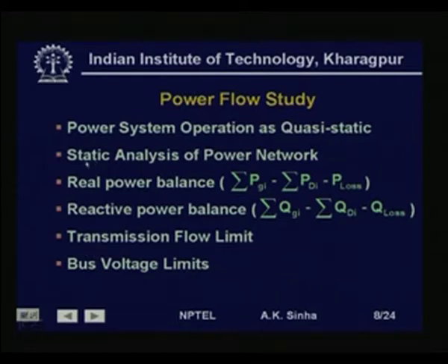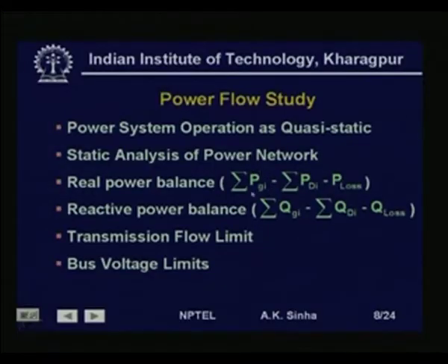Then we have real power balance at all the bus bars and also for the total system. That is, summation of all the real power generation minus summation of all the loads minus the loss in the transmission system is going to be equal to 0.